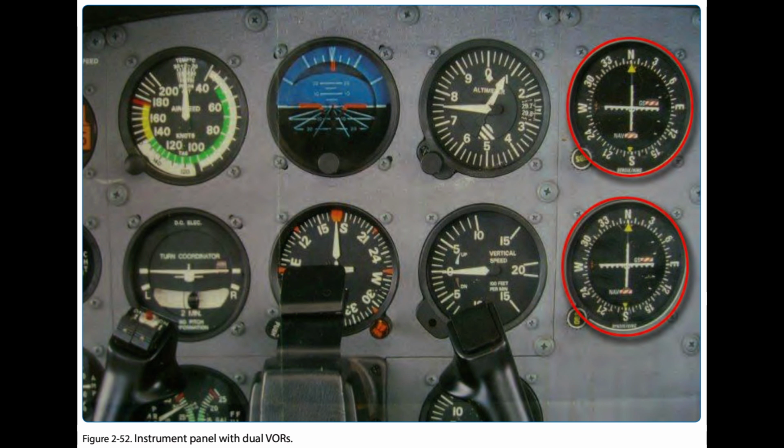Below is a list of generic checks that should be used when checking the accuracy of the system prior to flight. 1. System initialization. Pilots should confirm that the navigation database is current and verify that the aircraft's present position has been entered correctly.